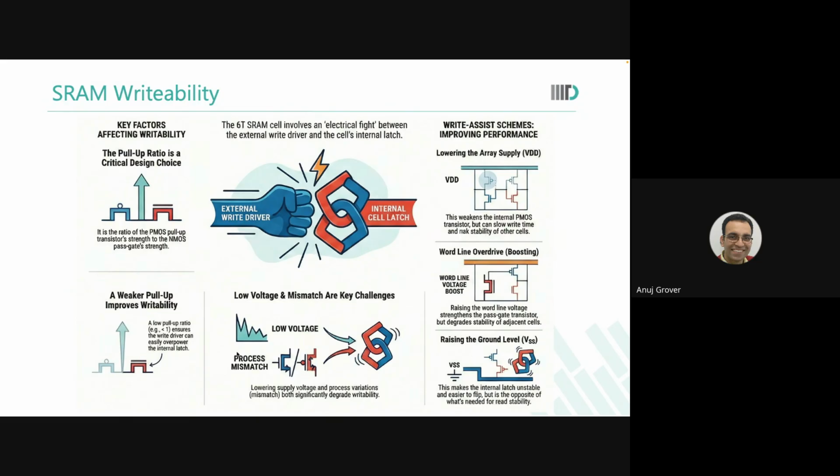And it is not simple because do you know the principle of how charge pumps operate? They amplify whatever voltage you're operating at. Whatever the VDD minus VSS you have, they kind of amplify a fraction of that. So you wanted 200 millivolts to be generated at 0.8. So you wanted a boost of 25%.